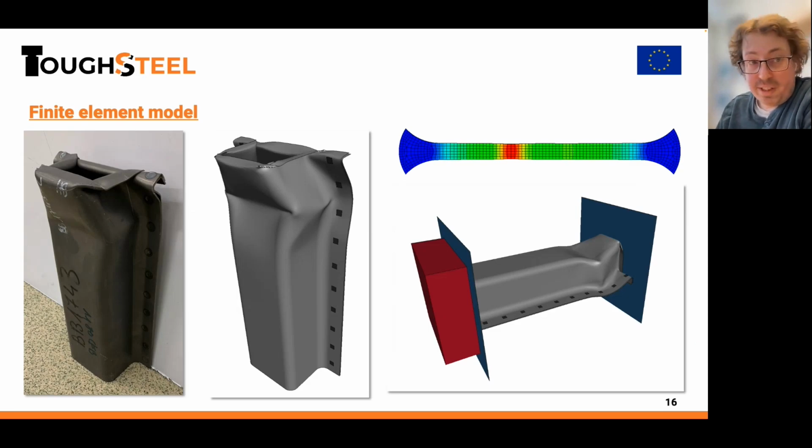And then we can implement it in a finite element model. In this case, it was of course a little bit complicated because it was pre-crushed, and to get the proper buckling before was a little bit tricky, but it was done in quasi-static conditions using an implicit time integration. And of course, the DIC used quite small facets, so the mesh size was calibrated for very small elements. So we had to do some mesh regularization here as well, because we used 1 millimeter shell elements in the model. Otherwise, it would be millions of elements, and that's just not feasible.